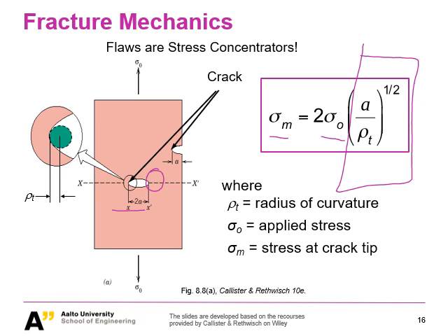If you have a really long crack, the stress here will be different. Or if you have rather a round crack looking like that, the stress here will also be different. So this factor here is really trying to reflect the geometrical differences of the crack.